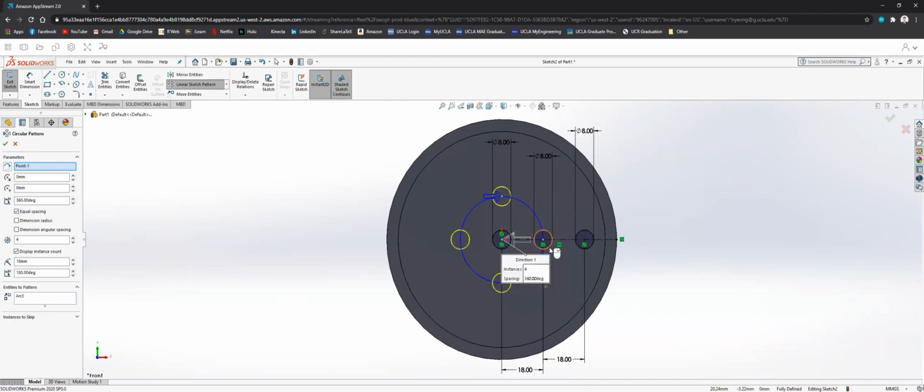I just click on that, and it's going to automatically generate the rotation. So it says 360 degrees, so it goes around at 360 degrees, and I'm doing it 4 times. So you can choose the number and adjust it accordingly. And it already tells you what the radius is. We already defined it as 18 millimeters, as you can see here. We could just go with this, and then we click OK.